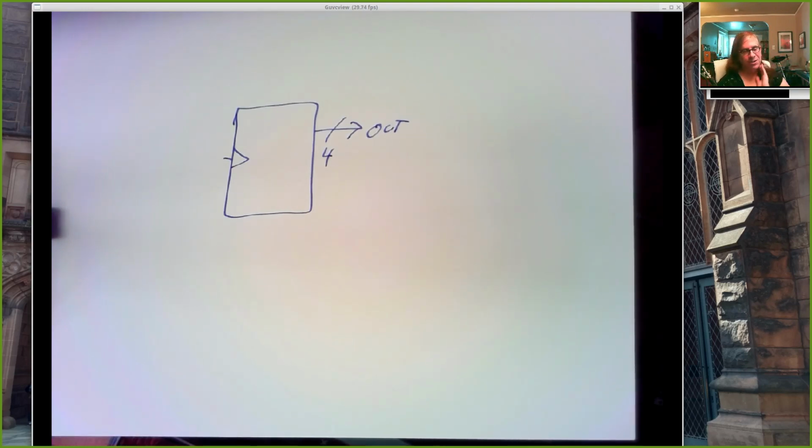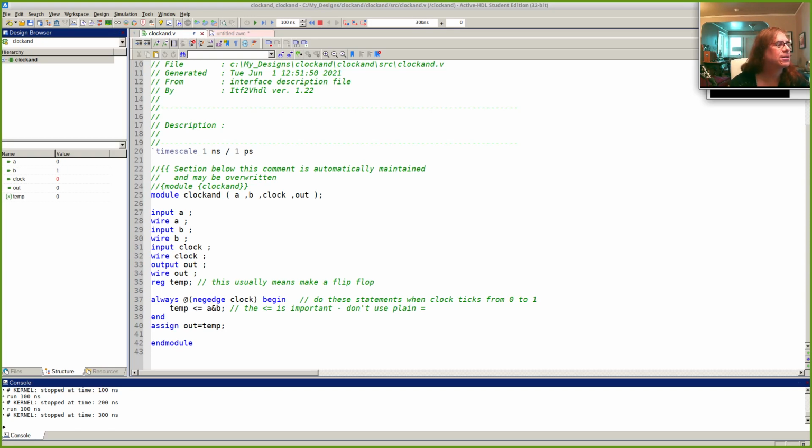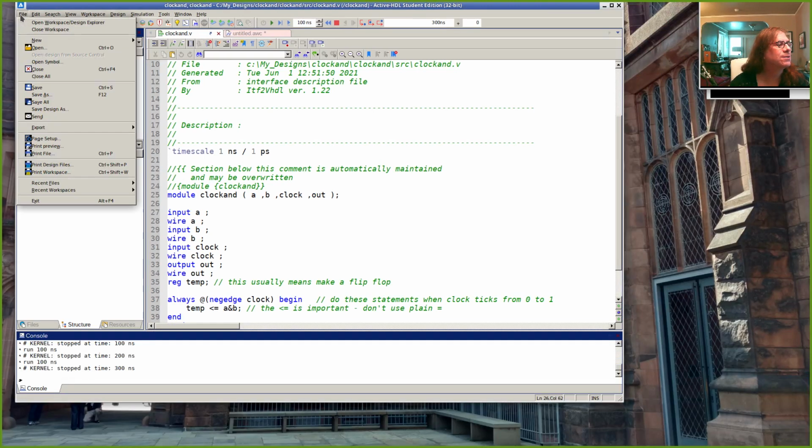And here we are going to have to deal with this business of what about unknown values. Because my Verilog code is basically going to be an always block, and I'm going to say when the clock ticks, let's set the output equal to the current output plus 1. So let's start that, but then we'll see a small complication.